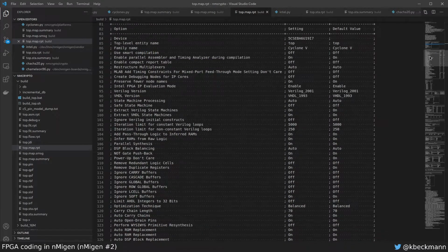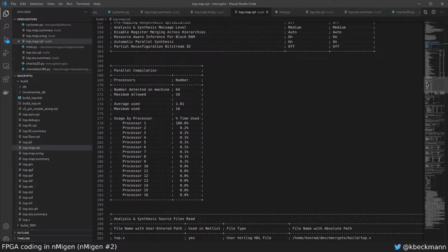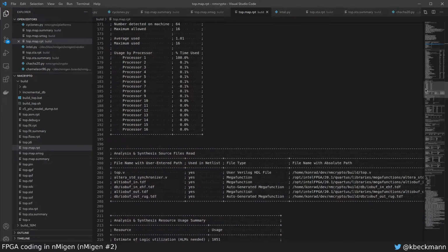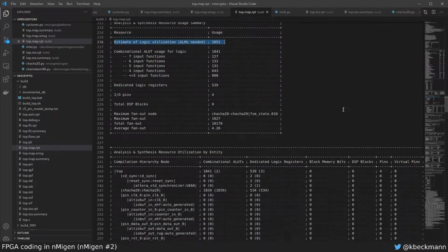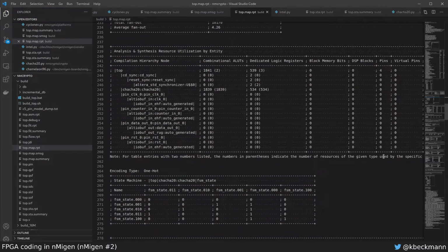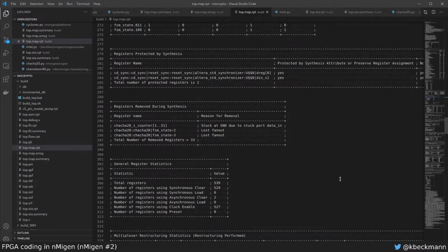So I suppose this happened because it failed timing. But here we have some ALUT, whatever that means. Arithmetic LUT, perhaps, I don't know. And ALMs. Okay, so it's an estimation, and then after it does the place and route, it knows for sure how many were needed.